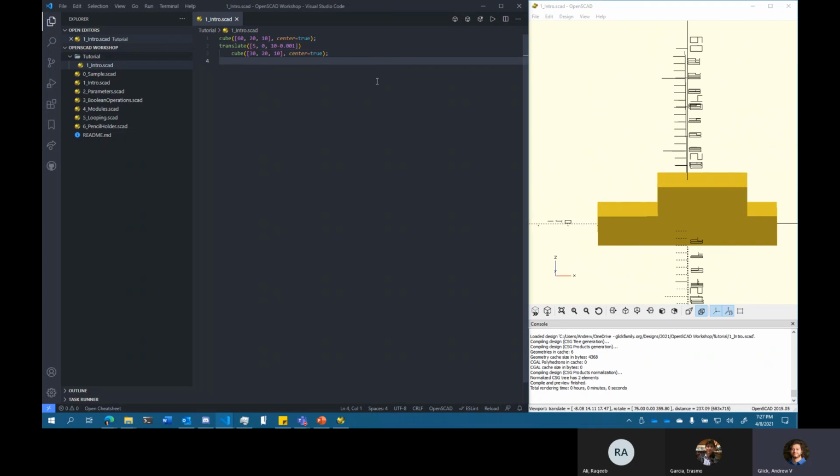And let's add a wheel now. So we can add comments. So this is the car body, and this is a wheel. So a wheel would be a cylinder. So we can say h equals 3, and actually, it doesn't matter the order, but I'll say r equals 8 for the radius and h equals 3 for the height.